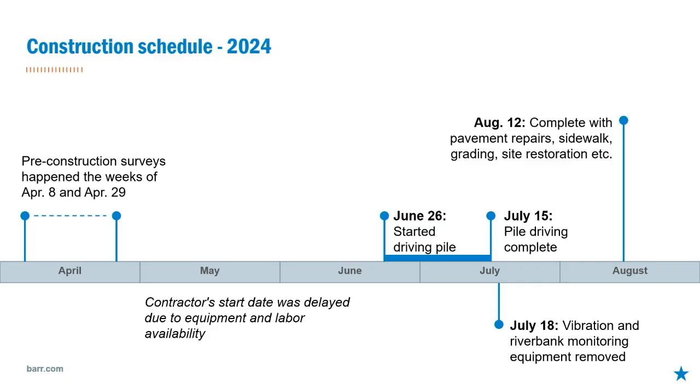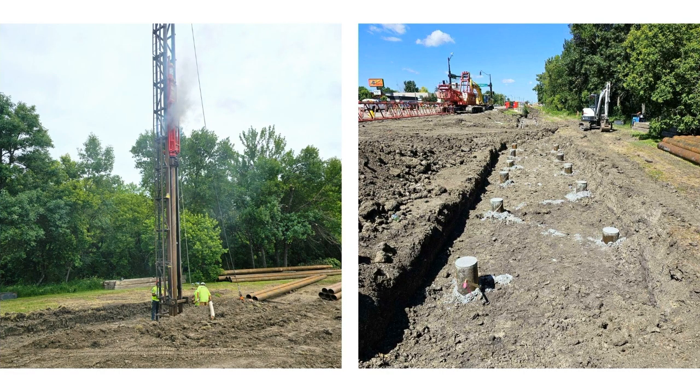So they ended up not starting driving pile until June 26th. But then that went relatively quickly. That was the main part of this project, done by July 15th. But we had the vibration and riverbank monitoring equipment removed by July 18th, and then all the repairs done by August 12th. So roughly a 2-month project. It was relatively quick once things finally got going.